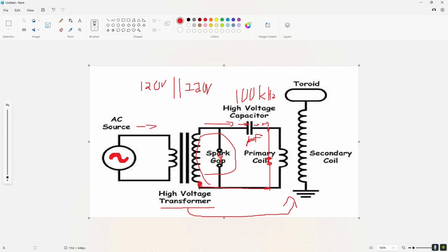Okay? If you're not that comfortable with that, because again, now they're getting faster, but the worry is that you don't know if it's gonna switch off fast enough to save your electronics. So you can get an isolation transformer. An isolation transformer will do exactly that. It's just 120 in, 120 out, and it'll have some kind of amperage rating. And that is the best way to protect your stuff, because it has the transformer in there, that core, and that makes it so that this line is completely physically disconnected from this line.